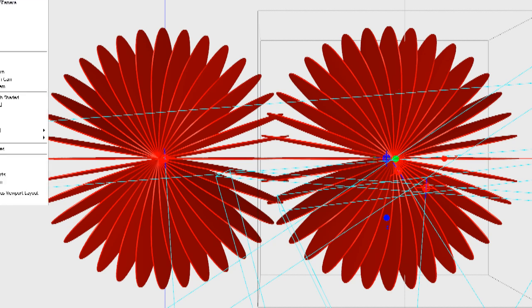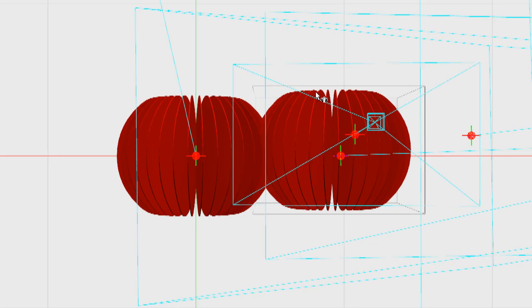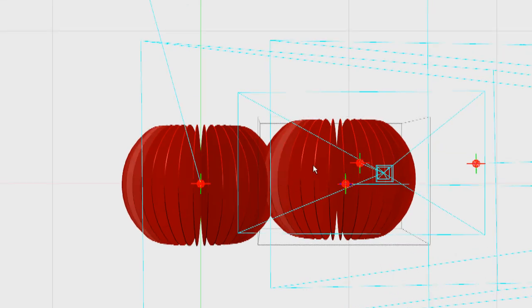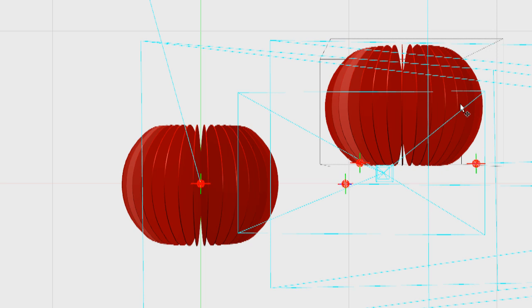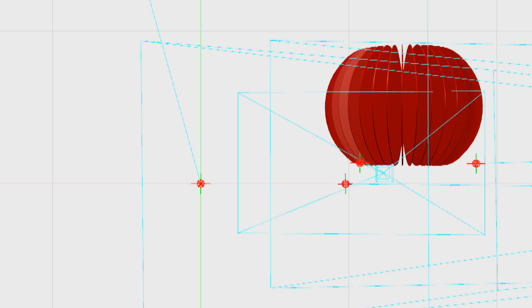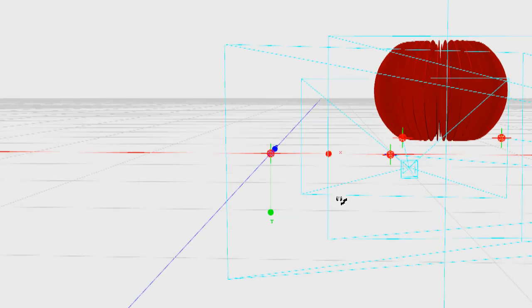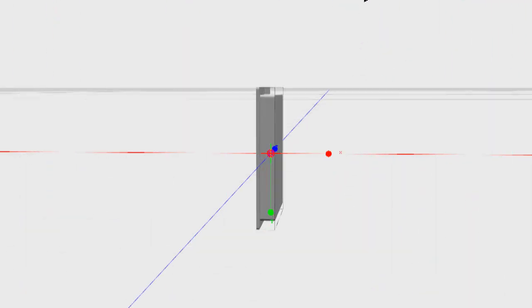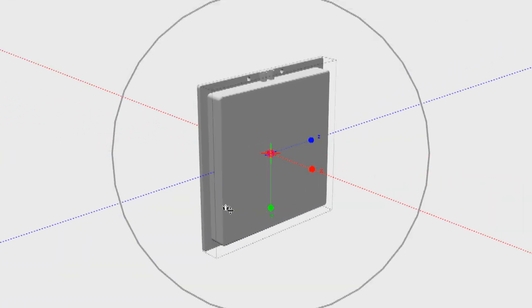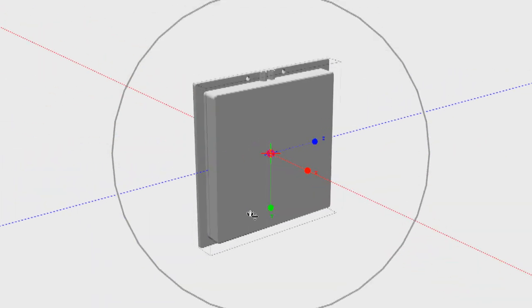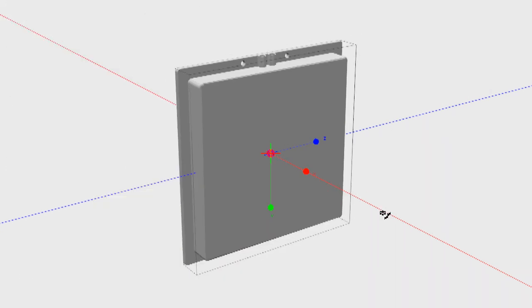Now, it's not the end of the world, because there are things that we can do, and this is the idea of diversity antennas, for example. So here's our plane. We'll leave the radiation pattern on that for clarity. We'll turn off our rubber ducky antenna, and let's have a look at a typical diversity antenna. Now, we're all familiar with the panel-based antennas. Now, this is a diversity antenna, which is 11 dB, so it's 11 decibel gain versus the 2 decibel for the rubber ducky.